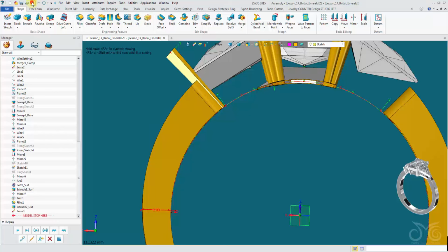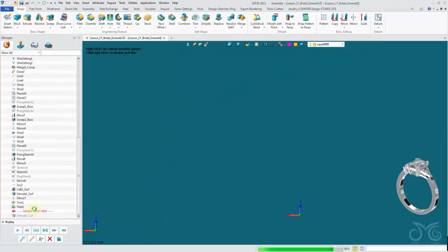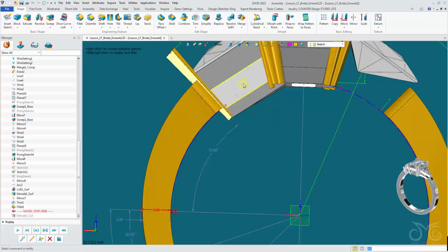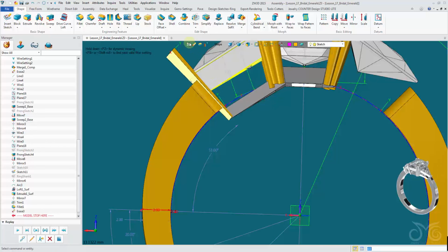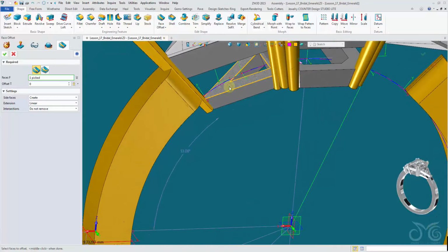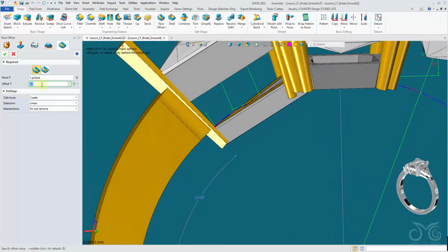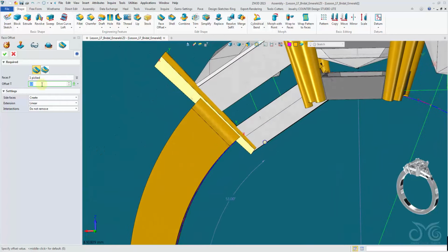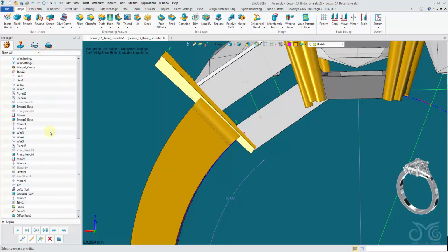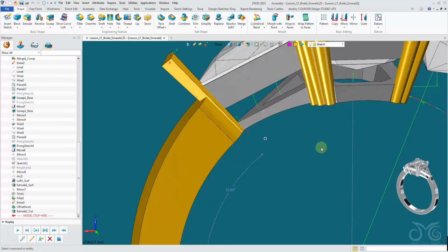In fact, I'm going to undo that erase, come back prior to the extrude cut, where we still have the entirety of our lower half. I'm going to erase these parts first, and then I will face offset this top face so it's above the ring finger. Okay, confirm there, replay the cut. Okay, now we have enough of the shape.